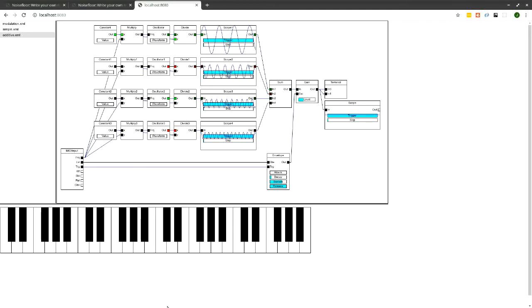So as you start adding those waveforms up in the harmonic series, you'll start artificially constructing more complex waveforms. And you can see that as that's pressed, we get that approaching triangular sized wave. Another principle there is if we take just the odd harmonics, we'll see that that wave starts taking on a more square appearance, and it starts thinning out and sounding a bit more hollow as well.